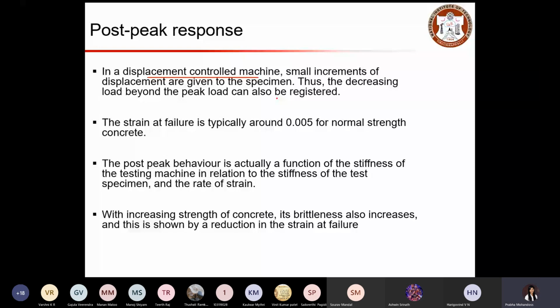When your test specimen is in the fixed condition and you apply a displacement, that displacement will lead to deformation and that will induce stress. So you are applying load in terms of displacement, by commanding your specimen to deform this much.